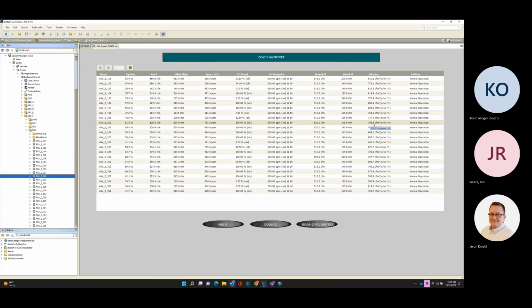And then I could probably take these off, and I probably definitely should, because you can set them. So these K factors, I'm going to remove these, Kevin, from this table so nobody accidentally messes with these. What I do is I put these on here for SCC. So when they do their TAB verification, they can go back and see what the balancer entered for the K factor when he balanced the box, and then what he recorded in his balancing report. So I do this as more of a courtesy for SCC.